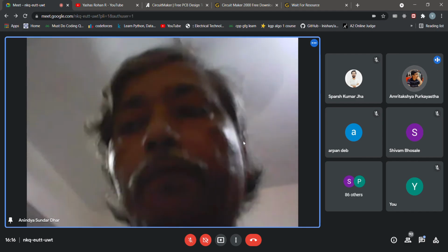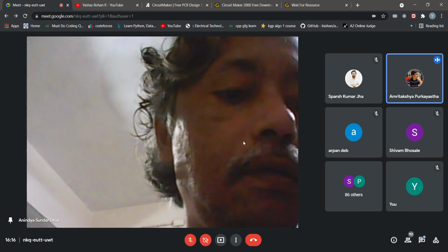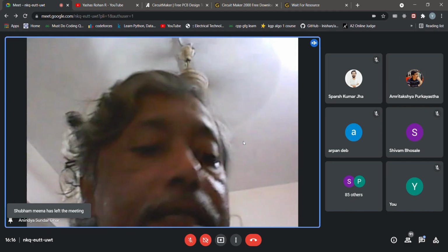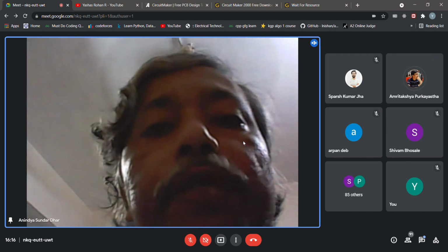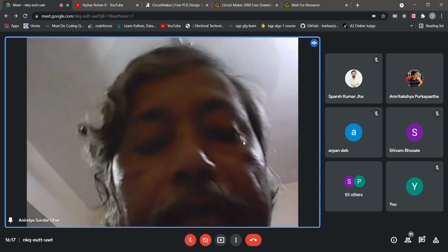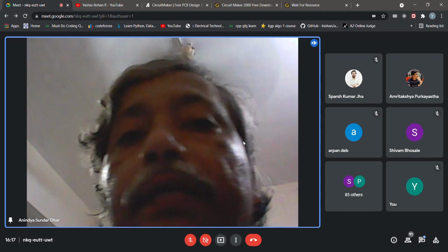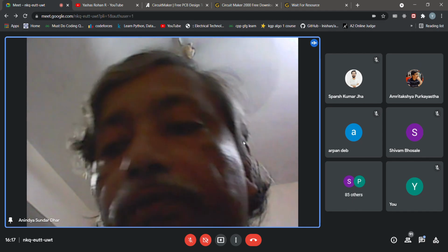In the 12-hour clock, how will you make sure that the second digit of the hour gets reset to 1 instead of 0? No, that is what I said, that maybe you need to have some tricky solution. First of all, you may think of whether you really require 7447 for driving that. Think about the 12-hour clock. Maybe I said that either 0 or 1, that digit will vary, that LSD if you call it.